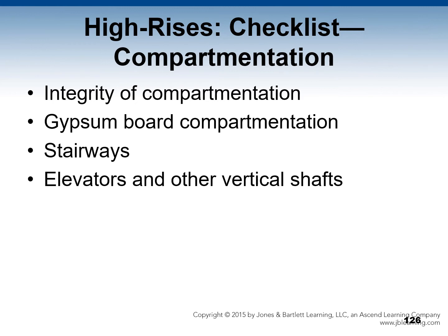And continuing down that list, you may have gypsum board compartmentation, which is actually what we started with earlier in the chapter. If you have gypsum board compartmentation, consider penetration of relatively lightweight gypsum partitions as a substitute for forcible door entry. In regards to stairways, are there deficiencies of stair enclosures? Are there proper operating door enclosures on all floors? Are stairways locked to deny entry to floors? Do all units carry forcible entry tools?